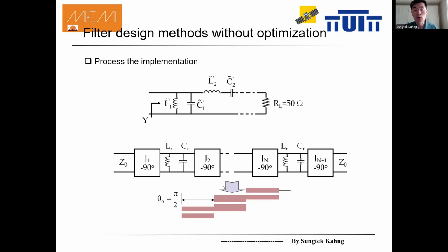as the coupling coefficient. Actually, we need one coupling coefficient between the two resonators. Say for example, you can eliminate this one between the two resonators, one, two, and input and output ports. Port coupling is also expressed as J inverter. Inverters are known to have a phase shift of 90 degrees, as you see.